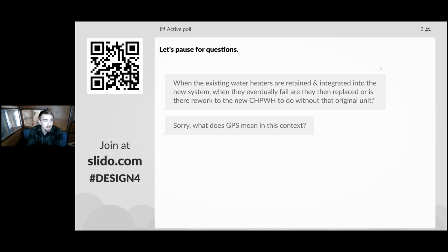So the integration of these heat pump water heaters, I guess we'll speak specifically to the Elizabeth James project here. We have 3 instantaneous electric water heaters that are paired with this one swing tank, and those heaters originally provided heat for the entire hot water plant or the entire building. So their primary function in this existing building is redundancy to back up those heat pump water heaters. So say if one of those heaters was to fail, then we would still have way more swing tank